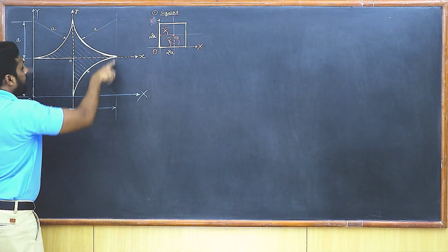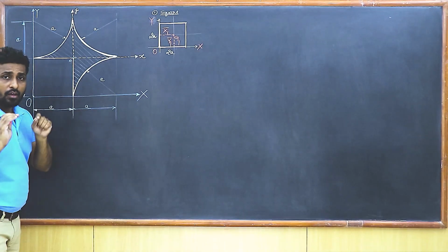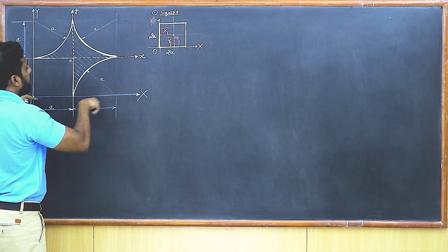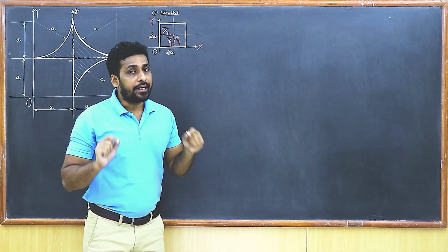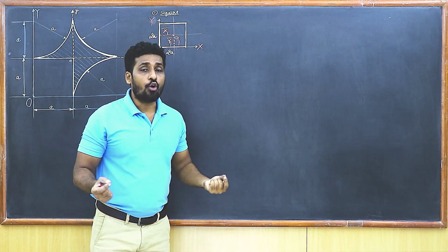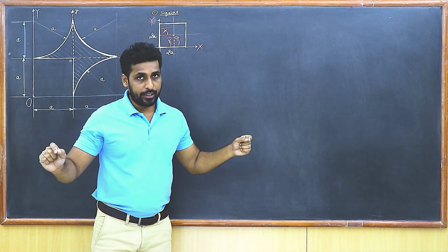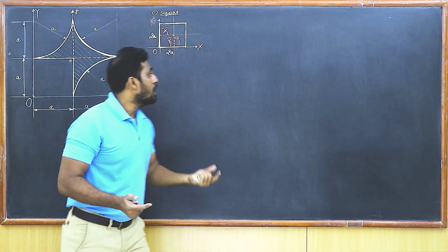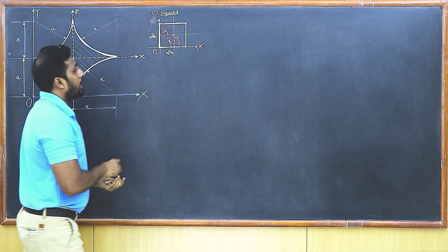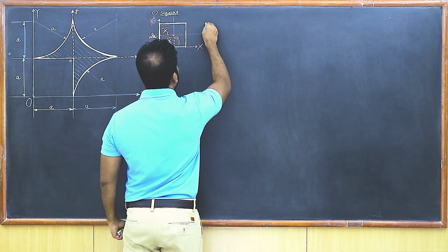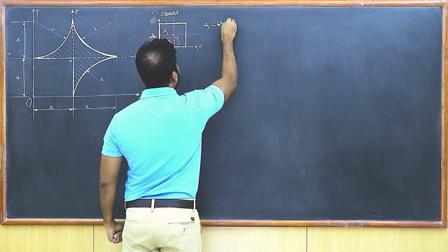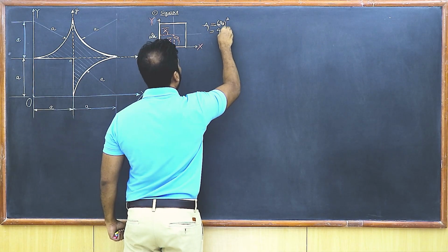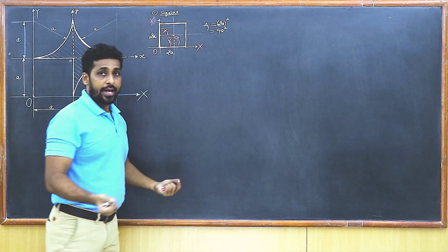The entire plane lamina now lies in the first quadrant, isn't it? Since it is lying in the first quadrant, you can easily identify that the x coordinate and y coordinate for all the standard shapes are going to be positive. So here, let's first of all write the area. So students, area A1 is going to be (2a) square, so that simply becomes 4a square square units.